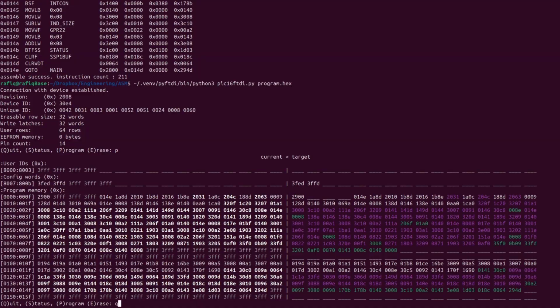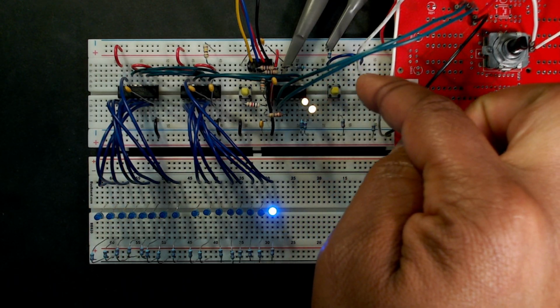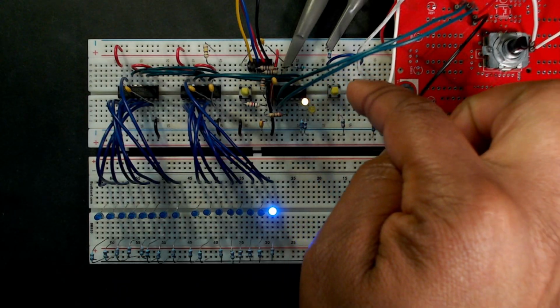Assemble and program. So now the buttons still work as expected. Now you may notice that a quick press sometimes isn't recognized by the controller. That's because it takes 65 milliseconds for it to detect the press, which is actually a little bit of a long time. I mean, we could leave things alone. It's really not that long of a time, but we can improve things a bit.